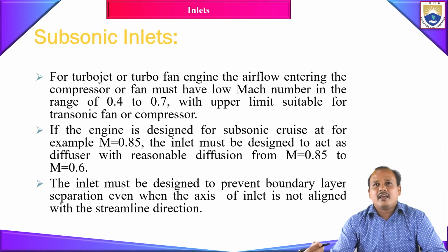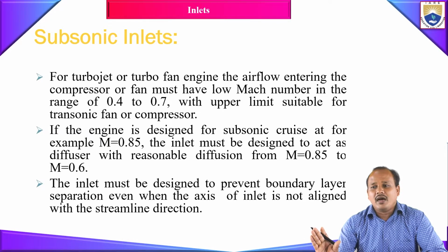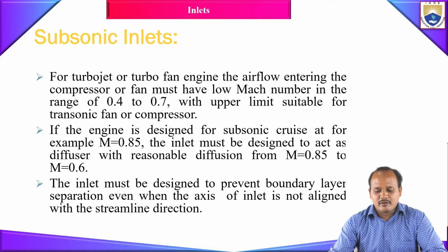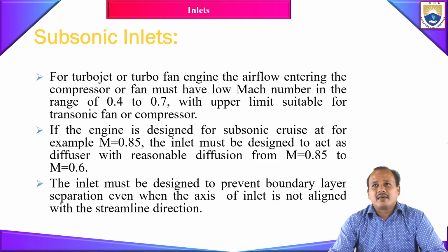So during takeoff or during cruise speed, the flow experienced by your compressor should have a certain Mach number. It should not exceed it. For example, for your compressor, the maximum Mach number at the compressor inlet should be 0.7 and the minimum should be 0.4.